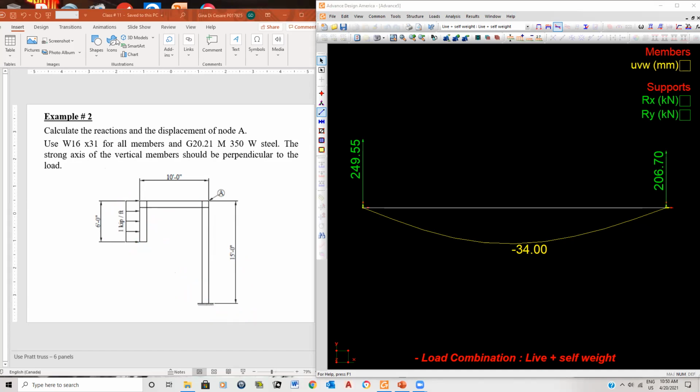So what this means is, since this is a Y flange section, this is the strong axis. In other words, where the flanges are parallel, this is the XX axis, okay? The program by default places them in a certain direction. For example, if I take a cross section here, and the program happened to put it in this direction, well, the wind is not acting with respect to the strong axis, it's acting with respect to the weak axis. In other words, it's the YY axis, and the same thing here.